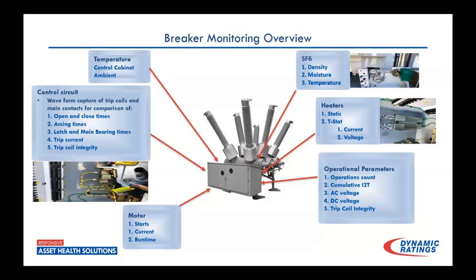I think the online method is really great in that it allows you real-time views of this data. Like I said, I've had a lot of people call me, and I experienced this at a utility. I get a call and a breaker's going to alarm. I got an SF6 alarm. Well, I have to call a crew out at that point. So now I'm rolling a truck in the middle of the night, and we go out there and find out that, hey, pressure's right where it should be for the temperature we're at.